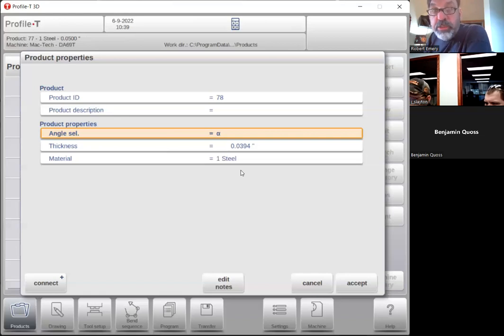Is it like a hemming tool or is it like a channel? It's not just a die. It's actually kind of like a press with springs in it. It's a forming die. We'll cover tooling, and there is some tooling you can program with springs in them, which are made for hemming. It's a 2-stage tool. It'll do a sharp angle and then you put it on the side and squeeze it. Those will have springs in them.